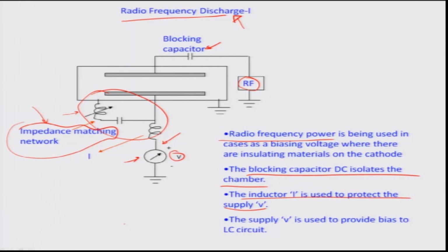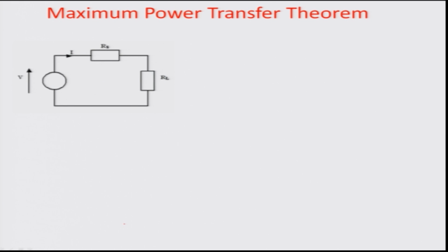So, let us suppose in a conventional case, there is a source resistance Rs which is associated with any power source and a load resistance RL, there is a way to formulate a maximum power transmission or transfer condition from the source voltage to the load resistor, and let us look at how we do it. So, supposing we had a current I in the particular circuit. So, I basically can be written simply by Kirchhoff's law as V divided by Rs plus RL, and power, as we know, across the load resistor is nothing but I squared RL.